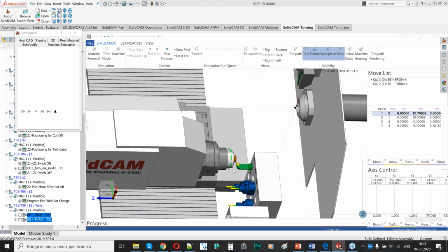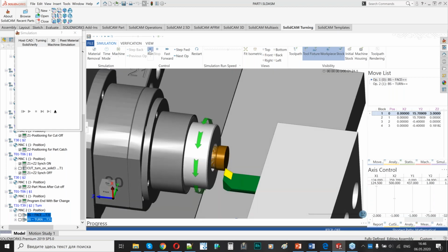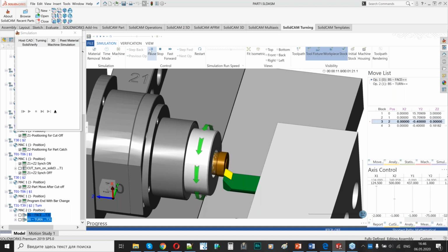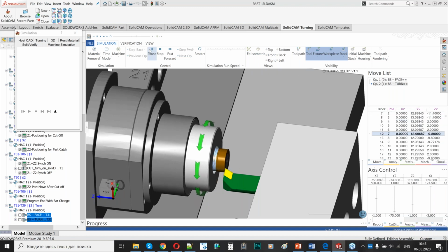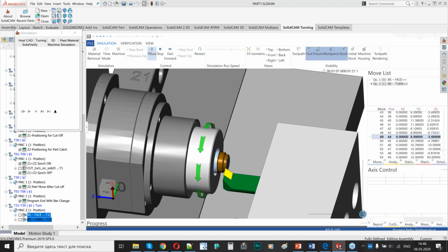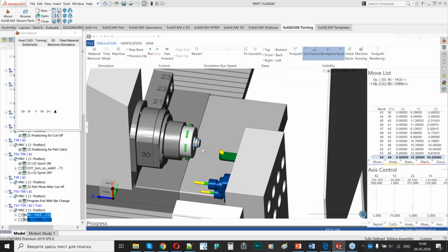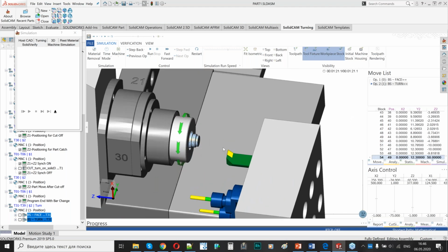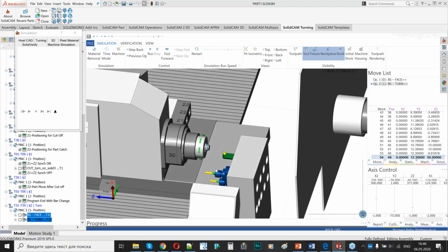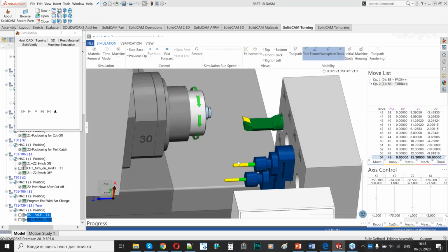Okay, what we have here, facing and turning. Because of these kinematics, I applied a long retract. If I had just a 2 millimeter retract, I would have problems when my part with the back spindle goes to other tools here. I would like to apply a milling tool because a gouge may happen.